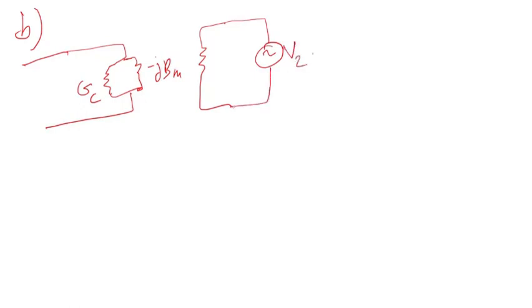So V2 is equal to 120 because we applied it to winding 2, and the circulated current is I2. Then obviously you will have voltage here, and the ratio on this side is 480 volts, this side is 120 volts.